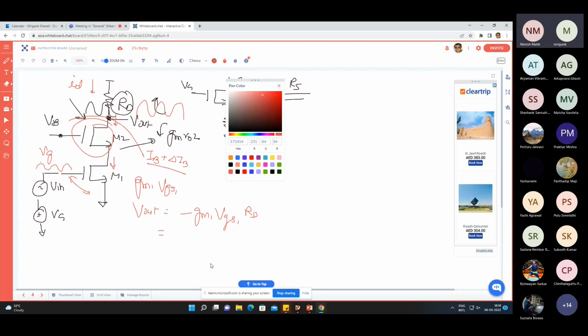There will be a voltage drop across both M2 and M1. So if VB is fixed and the gate voltage of M1 is fixed, you want to find out the minimum value of the drain voltage you can tolerate. So what does that mean? Is that going to affect the source voltage over here very significantly?